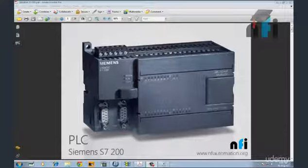If you look at this PLC, in the top you can see Q0.0 up to 0.7 and Q1.0. So these are the digital outputs of this PLC. We are using the model S7200 with CPU 224XP in which we have digital outputs. And at the bottom you'll see I0, so I stands for input, Q here is the output. So from I0.0 to 0.7 these are the inputs, then another set of inputs up to 1.5.